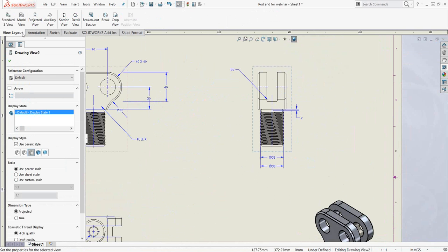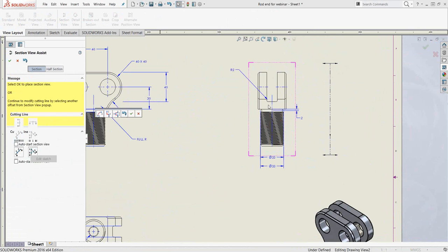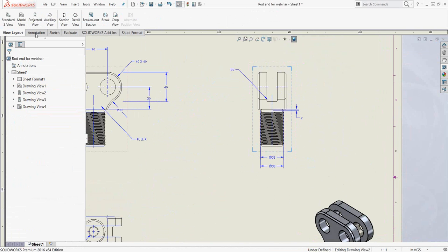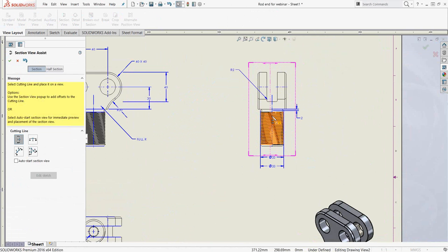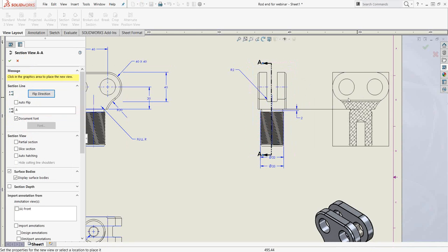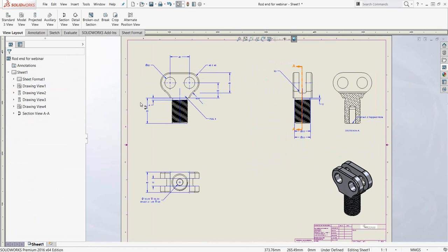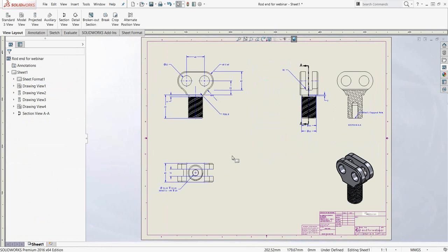which is great, especially if you're, say, creating a section view. So if you want to create a section view of that view, you can grab it, drop a section view in here somewhere, and then it'll create that section view over here. And then you can drag and drop those dimensions where you want them to be, right? So if I create my section view here, my green check, I can bring that over, and then I can drag and drop dimensions over there as needed, right? So I don't have to actually redimension things. So a great tip on the views.